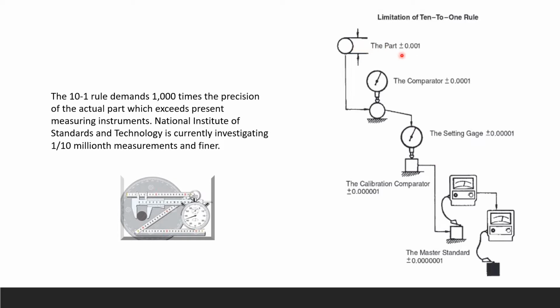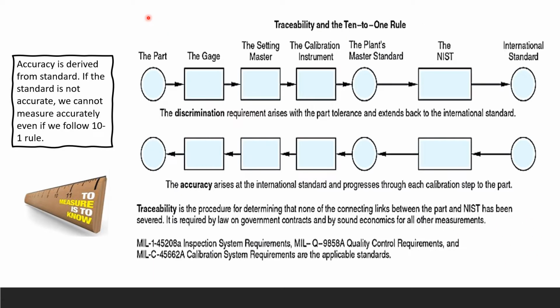If your part is here, you calibrate with this. You can also calibrate your instrument with this. We calibrate this instrument with that, and this and that. That's how you trace all the way back to the original standard. Okay, traceability and your 10-to-1 rule.